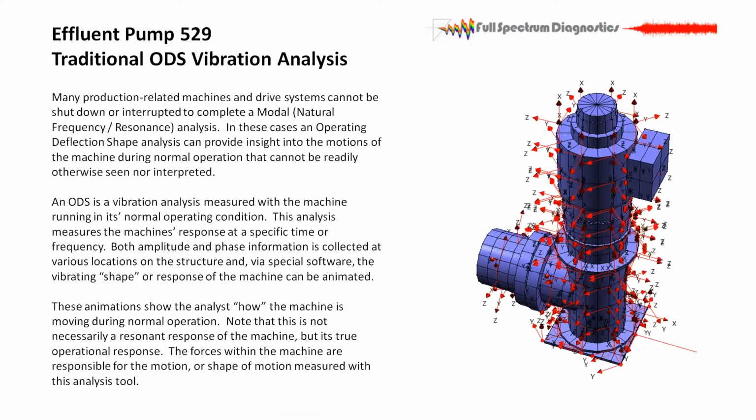Okay, so we did this ODS vibration video. We found vibration in the machine that wasn't all that big. We found modes that were combined, potentially a natural frequency or resonance phenomena. We found a source for that in that binding in that discharge line was changing the natural frequency, possibly pushing it into the operating speed range. And we looked at the foundation and it didn't seem like there was a big deal there. That didn't seem like the root cause.